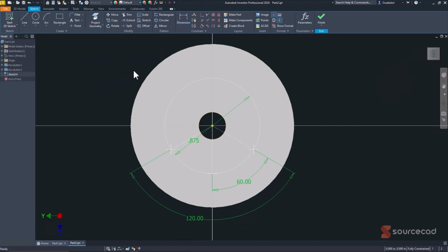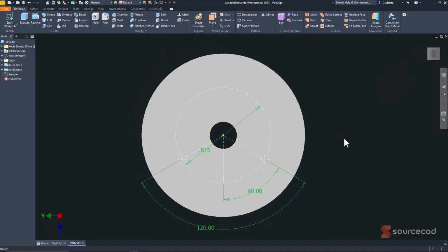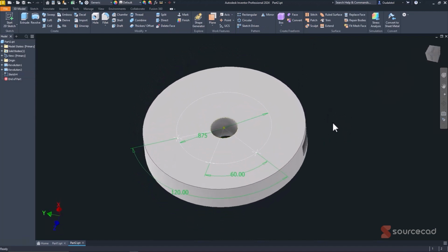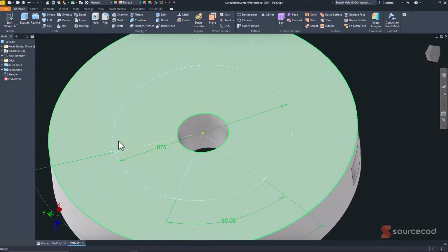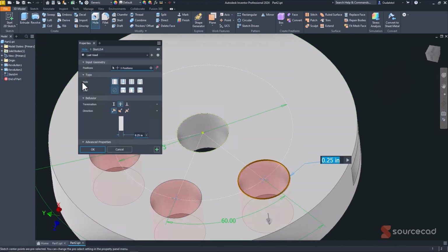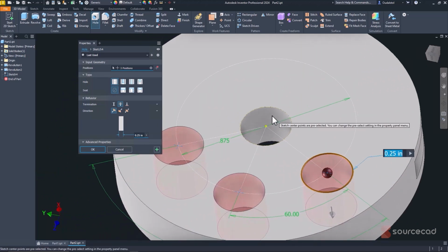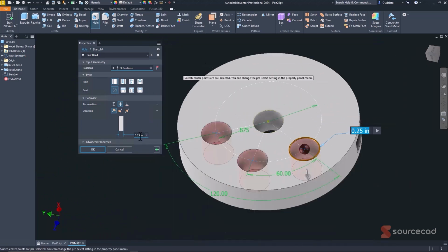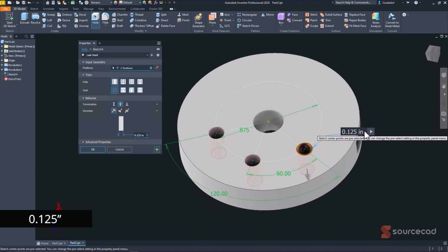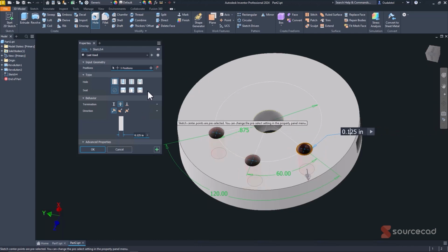And I want to click OK. And so if I click finish now, you will see you have a sketch, and it's white on white. A sketch with 3 work points. So if I hit the hole command, it actually automatically understands you want holes here on all 3. So I can change the number out here in this dialog box, or actually just right here, depends on all your preference. Let's do 125. And I'm going to cut them all the way through.